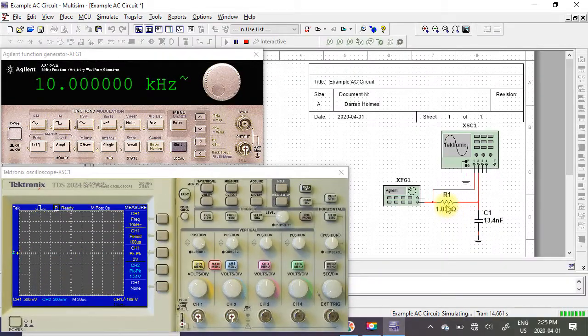One is to swap R1 with C1. Changing their positions will not affect the circuit because it's a series circuit and the same current flows through both components. Rather than changing our circuit, we can also find out what the voltage drop across R1 is by taking the total voltage across the circuit and subtracting the voltage across C1.